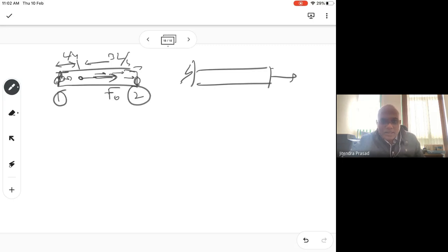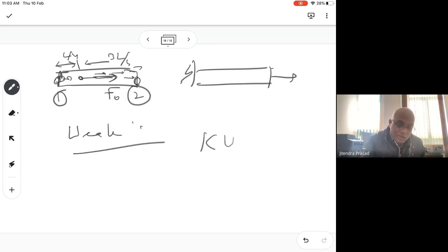Any other question, guys? The weak form is important because you know exactly how to find the stiffness matrix, how to find the force vector, and how the equation will be Ku equal to F. Weak formulation gives you exactly Ku equal to F and automatically puts things at the right places.